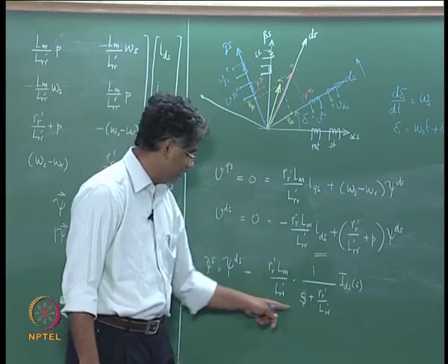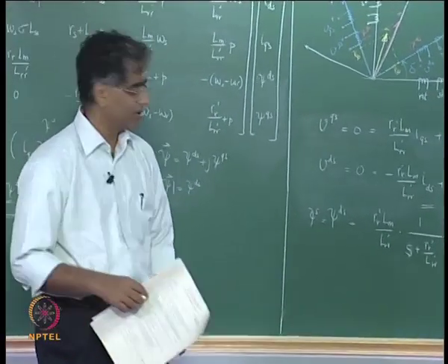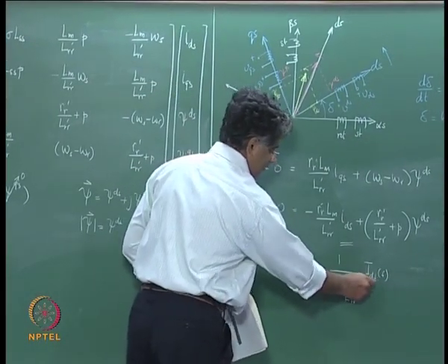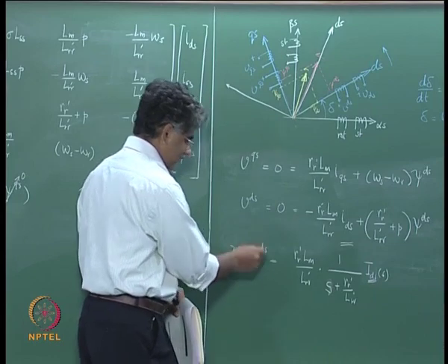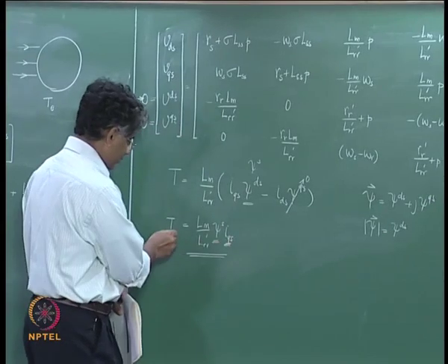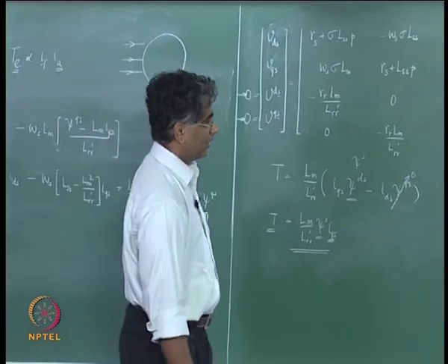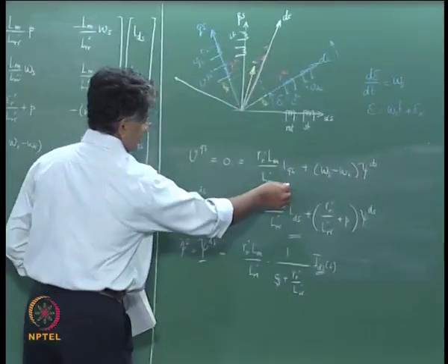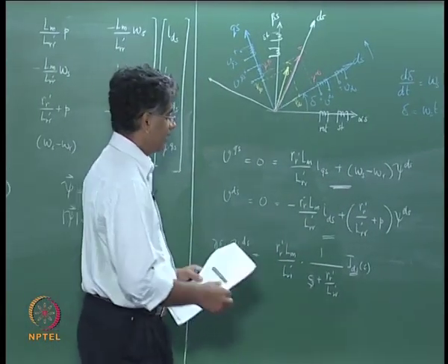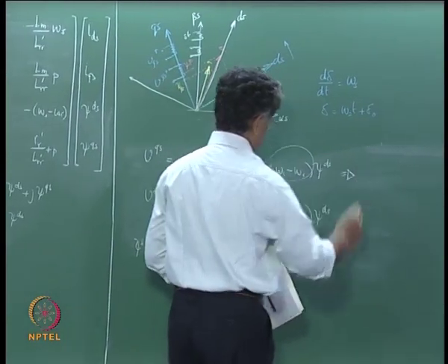This is related only as a simple first order equation, which is again similar to that of the field in the DC machine. So, we can say that IDS controls the flux in the machine, whereas IQS determines straight away the generated electromagnetic torque TE. And one can get from this equation, if these two are met, an idea of the slip in the machine.